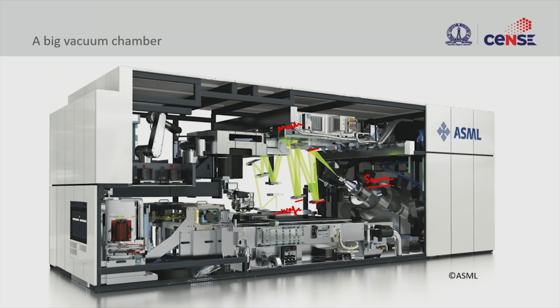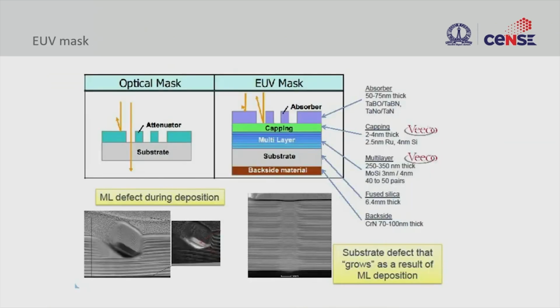At the same time, they should be in a chamber. That is the reason why all these challenges, including source stability and alignment stability, the mask technology and the resist technology, keep extreme UV from hitting the required production scale, which is still being delayed.